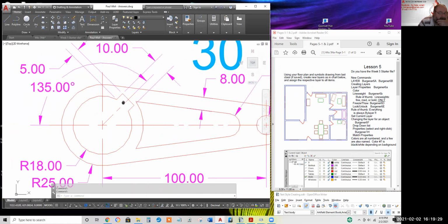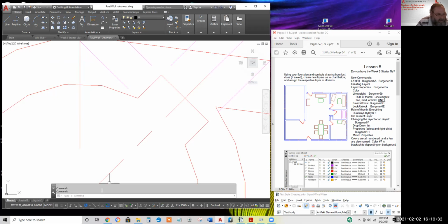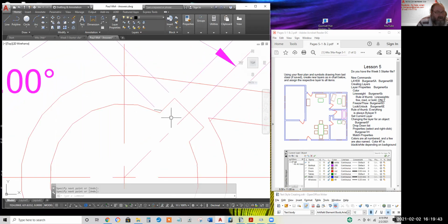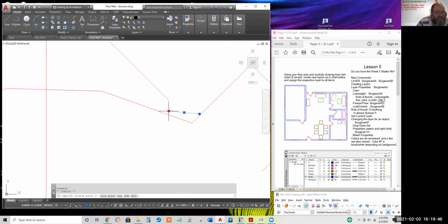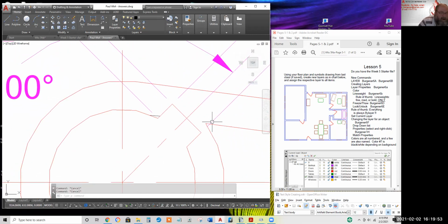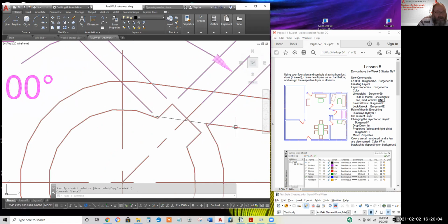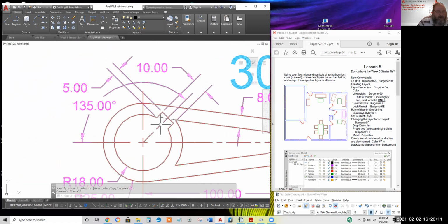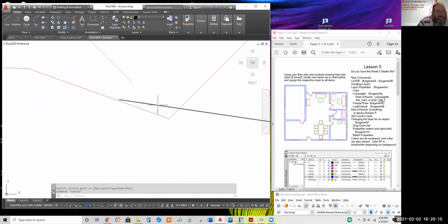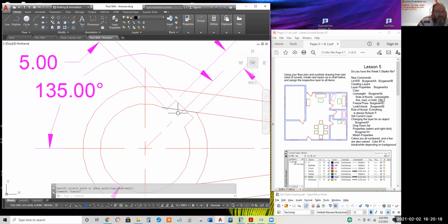Three of you I noticed had a little glitch. Turn off object snaps temporarily. You had a little line about right there, touching the object line. It took me a while before I realized that line perfectly lines up with this line. So what happens when you created this diagonal line here, you trim away. I assume those three were zoomed out so far, they didn't realize that they orphaned this tiny little whisker there.